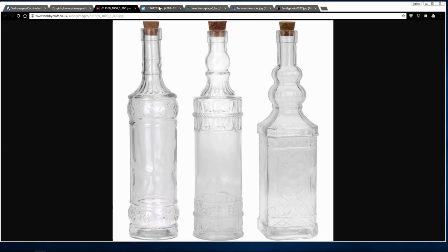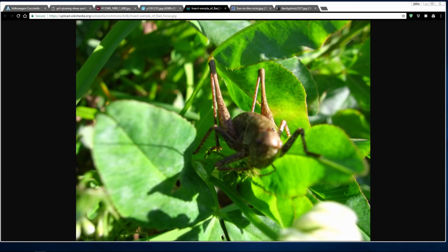Also, you cannot use blurry images, and if in an image set there are 2 or 3 images that are blurry, it will not work. So be careful not to move too much, and make a good focus. For example, this one has a bad focus on the head, so it will not work for this kind of picture either.